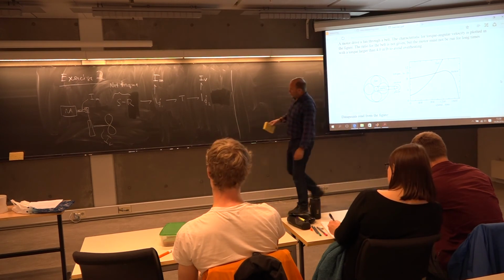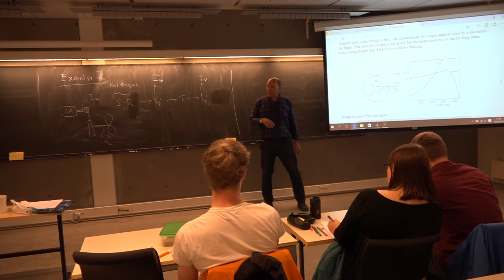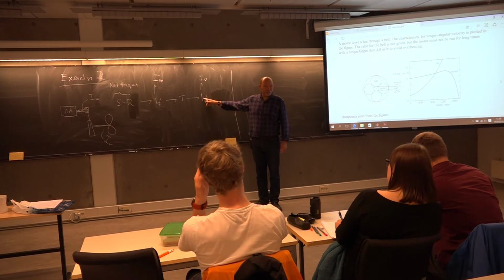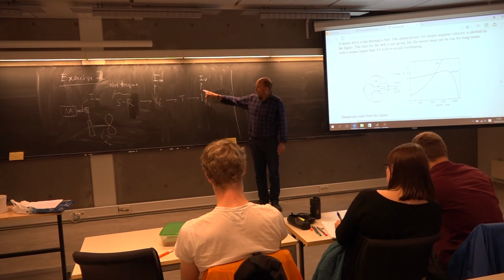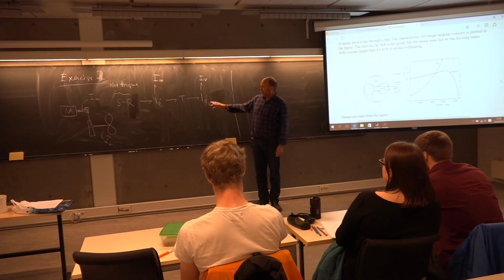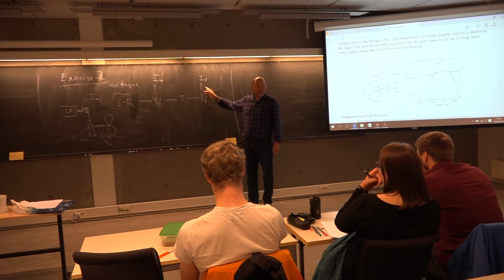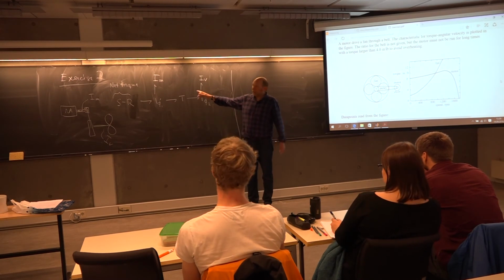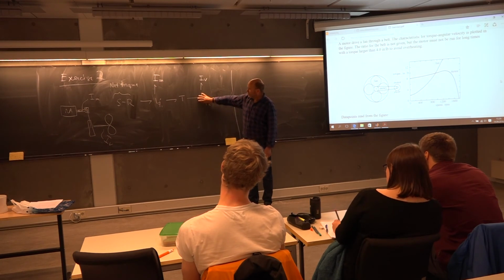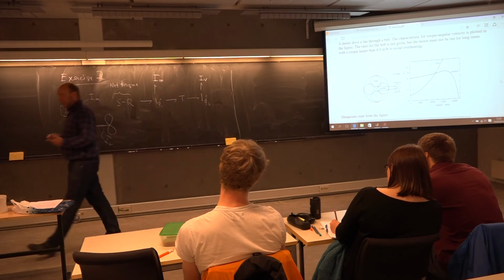And now you see on the other side here, it's now possible to simplify this a lot. First of all, this one junction here can now be removed since it has only two bonds. So it doesn't do any good anymore. It's the same flow on these two bonds. Well, then the effort has to be the same as well. So it doesn't do anything. Then it can be removed. And then we are given a cute little trick.